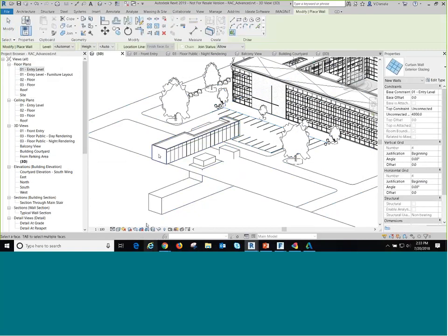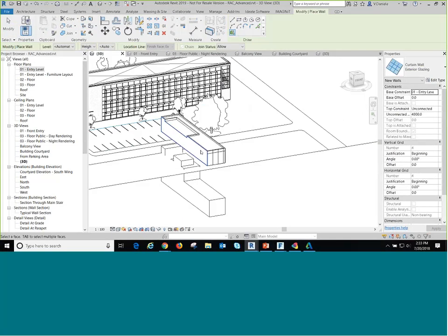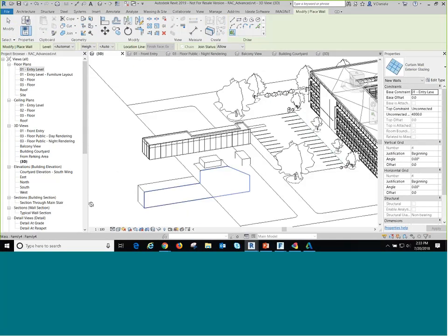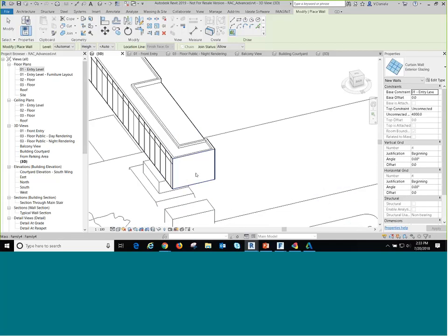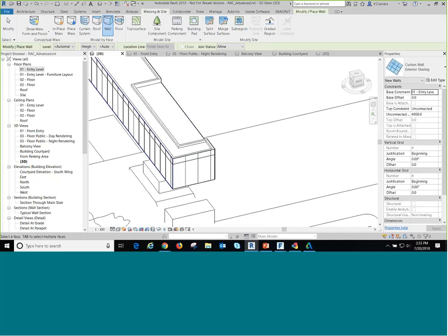With apply wall to face, we can slap actual Revit components onto the massing. And because it is a conceptual mass, if you update the mass in the mass family and you're using any of your massing tools like curtain systems, walls, roofs, floors, if the mass updates, you can automatically update those components to match the conceptual massing.